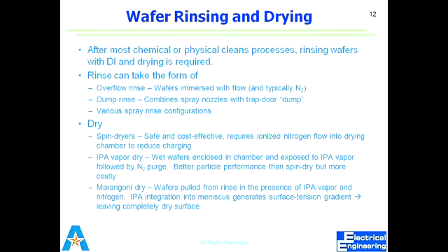So when you take it out very slowly, there should always be a meniscus between the IPA environment and the water. At that meniscus, the IPA gets absorbed in a very thin layer, so there is a gradient between the IPA concentration at that meniscus and in the surface of the water.